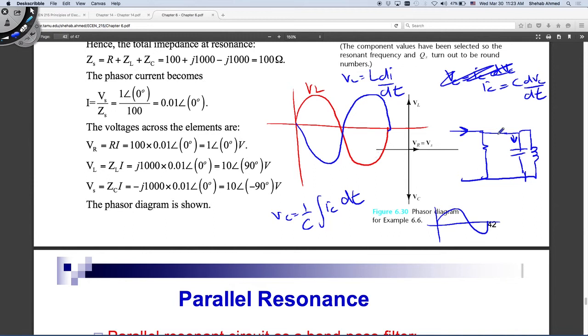That's the corresponding voltage at the terminals of this circuit due to the current that I've injected, assuming you're able to inject this current in there. So if the result is a terminal voltage across the capacitor that looks like this, blue, and a terminal voltage across the inductor that looks like this, red, then what is the terminal voltage across these two nodes here? 0. You have two voltages that are opposite in polarity.